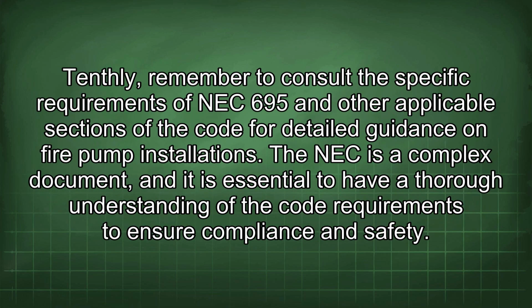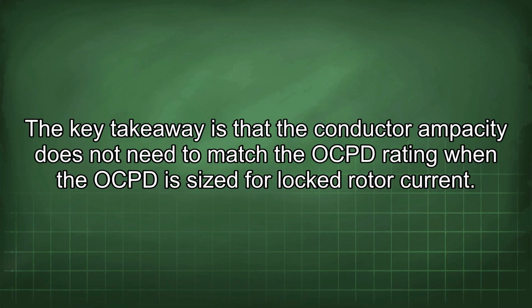Tenthly, remember to consult the specific requirements of NEC 695 and other applicable sections of the code for detailed guidance on fire pump installations. The NEC is a complex document, and it is essential to have a thorough understanding of the code requirements to ensure compliance and safety. The key takeaway is that the conductor ampacity does not need to match the OCPD rating when the OCPD is sized for locked rotor current.